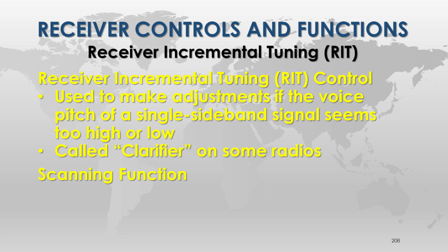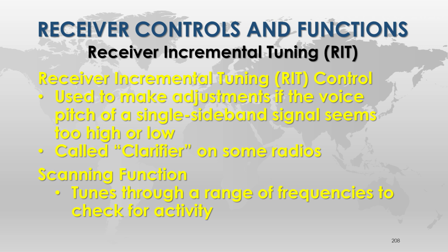Scanning function. This is different now. It's not receiver incremental tuning. It tunes through a range of frequencies to check for activity. You can scan the entire band, or you can scan just your memory channels that are programmed in. It depends on the mode that you're in. If you are in memory mode and you set it for scan, it's going to scan the memories. If you are in VFO mode, it's going to scan the band.